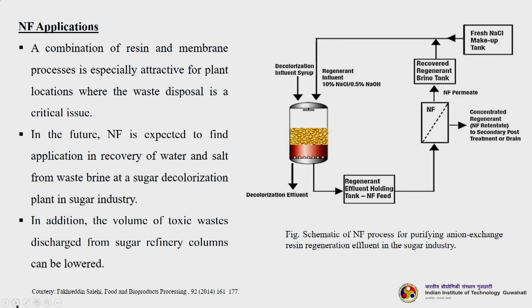Another NF application is purifying anion exchange resin regeneration effluent in the sugar industries. Here, a combination of resin and membrane processes is especially attractive for plant locations where waste disposal is a critical issue.